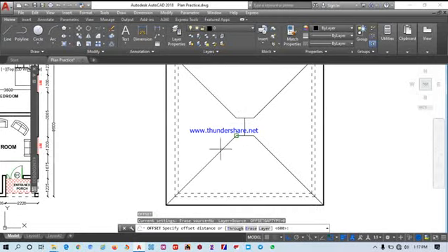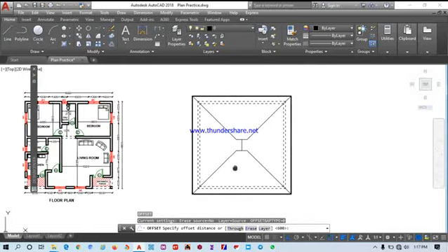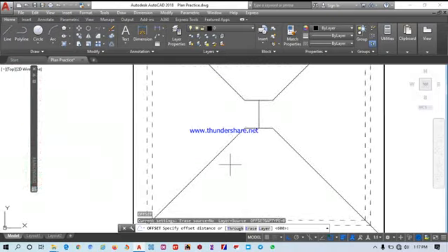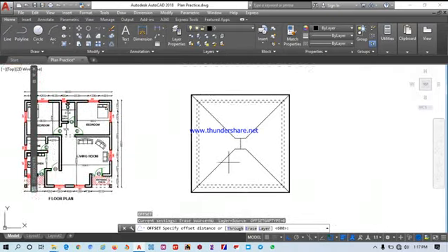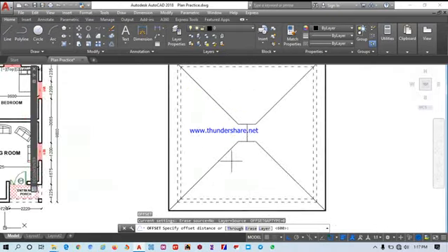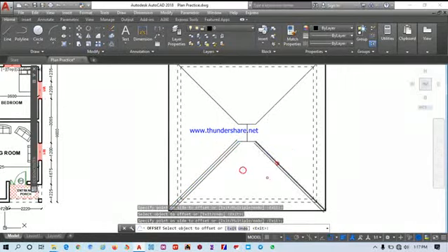This is our ridge. The roofing sheet covering our ridge is what we call a roofing ridge cap. The ridge cap is 300 mm in width. So to show that, we have to offset 150 on both sides of the ridge to create the awareness that there is a ridge cap here, to illustrate that on our roof plan. So can we see it's quite simple?